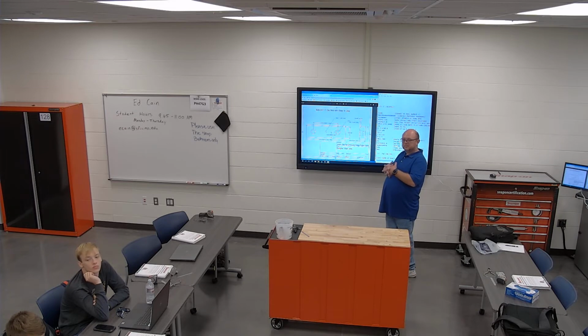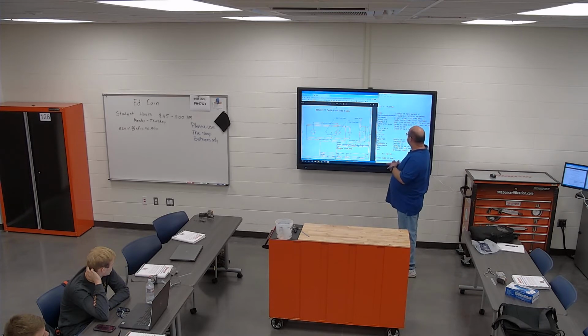Does it have to be T1 and M06? Because you do M06 T1. And that doesn't matter. The spacing also doesn't matter. It reads the whole line at a time. Right, I just want to make sure it was the same as you would put it into the MDI screen, that you can flip flop. Yeah, you can flip flop. You can flip flop any of these as long as on the side.